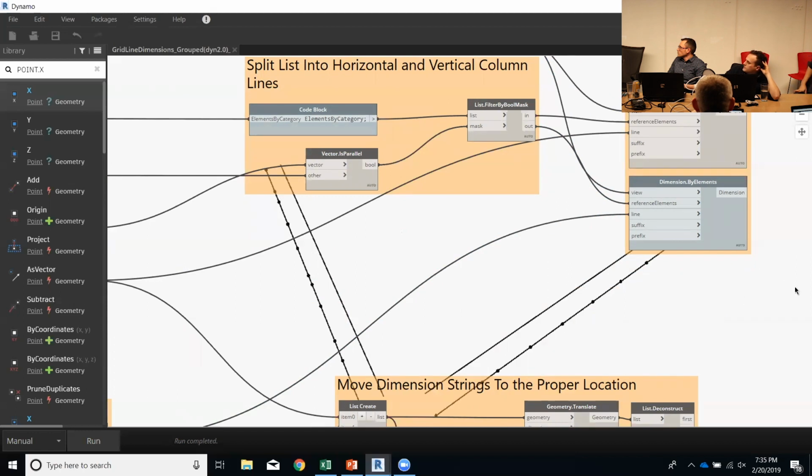If you first have part of a script that exports out element IDs, and then your second script reads those element IDs and checks them before it does something to them. So in that case, once you close Dynamo, it's no longer connected unless there's an element ID to connect the script to the file. So double check it before you apply it.